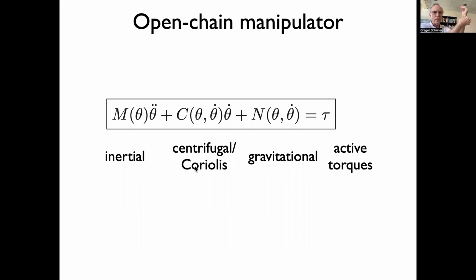So if you accelerate your wrist position, then there would be some torque exerted on the hand that would make it flip back. And that would be an interaction torque, interaction between the joints, right? So some acceleration inserted into this through a torque that I apply to the elbow joint induces some acceleration at the wrist that is reflected by an apparent torque coming from the non-inertial frame at the wrist joint. And that torque we call interaction torque.